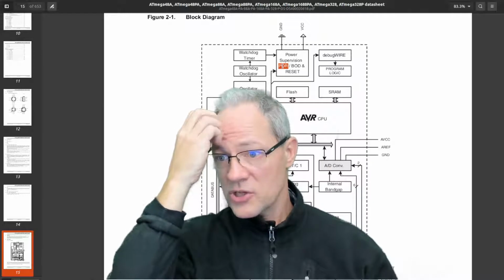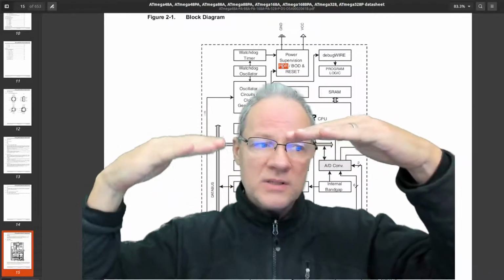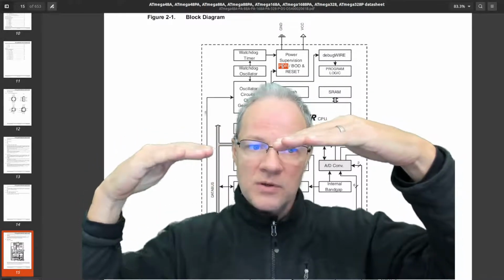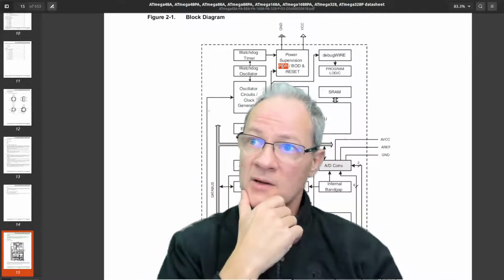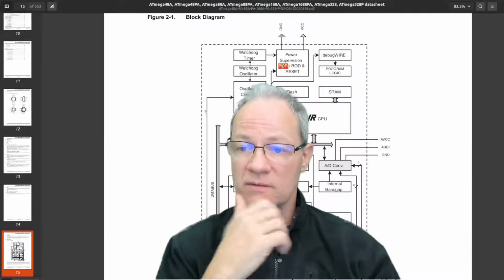So POR means power on reset. Right? It may also check for brownouts. For example, what if the power is not stable enough, what if it lowers for some time, or what if it spikes? Then we also may not sustain a stable performance of this device.